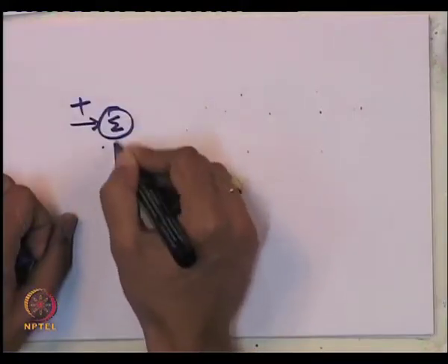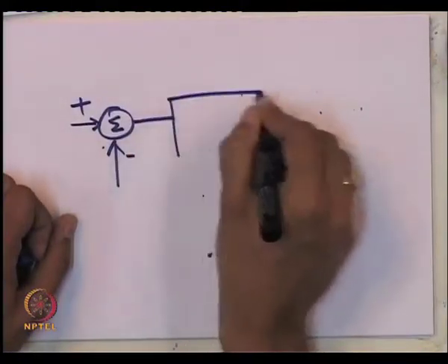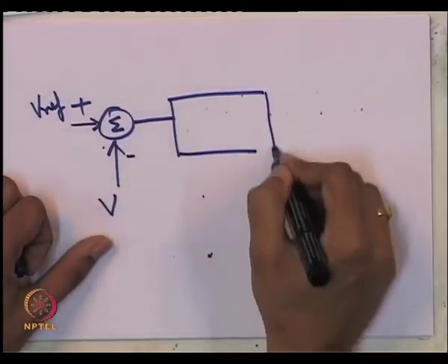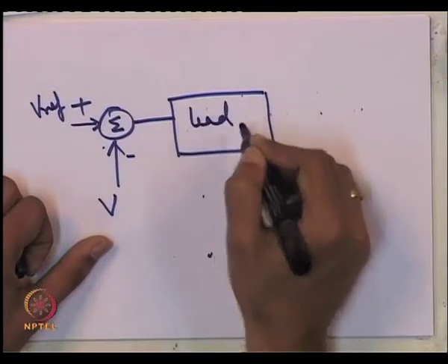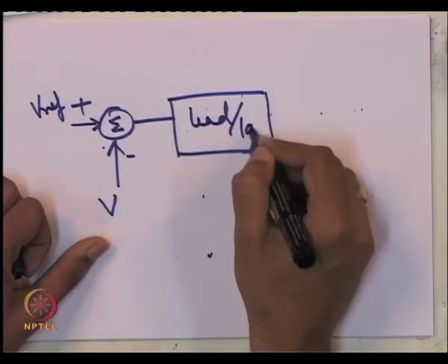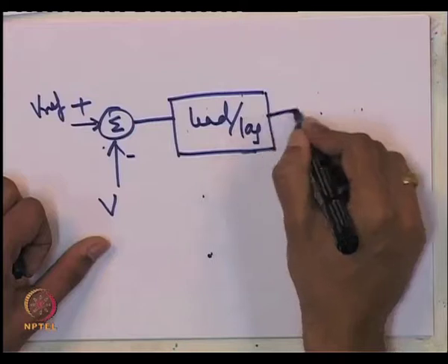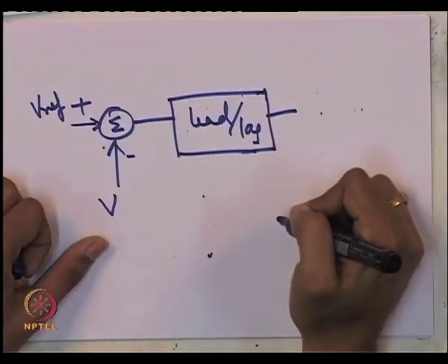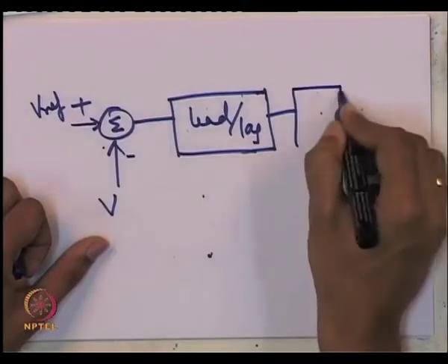So, this is very important, which you should note. If you look at a typical regulator, it does not consist of just proportional controllers. Typically, you will find that it consists of Vref, V, a lead or a lag block, usually depending on the situation you could use, most likely you will use a lag block if you want to achieve some functionality.